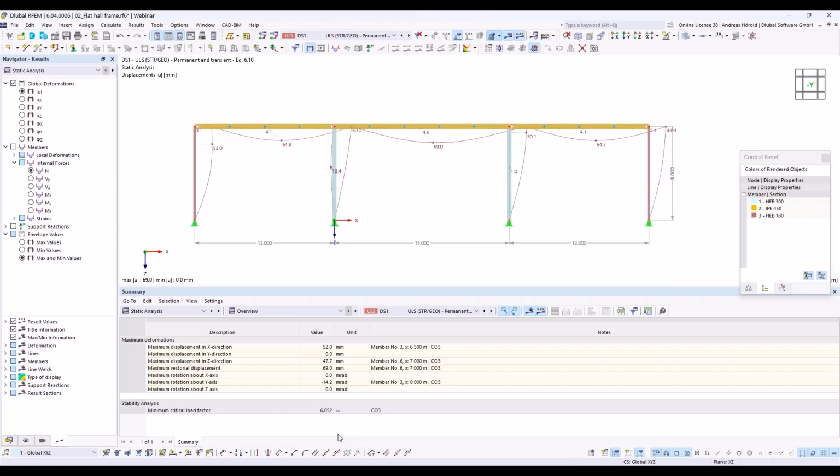But what I already mentioned, for the stability design using the classic equivalent bar method, means method C, the internal forces can be calculated according to geometrical linear analysis, and buckling lengths must be assigned to the columns. But for the design of the lateral torsional buckling, the application of the second order analysis is also required with this method.